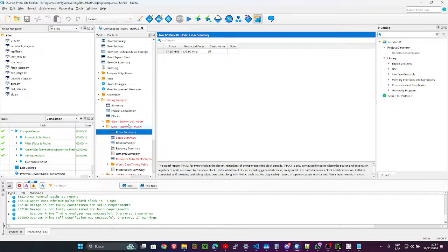Because it is assuming your FPGA is literally at 80 degrees Celsius, which makes everything slower and more power consuming. This is the worst case scenario, essentially. 80C: 124 megahertz. Worst case, 120 megahertz.